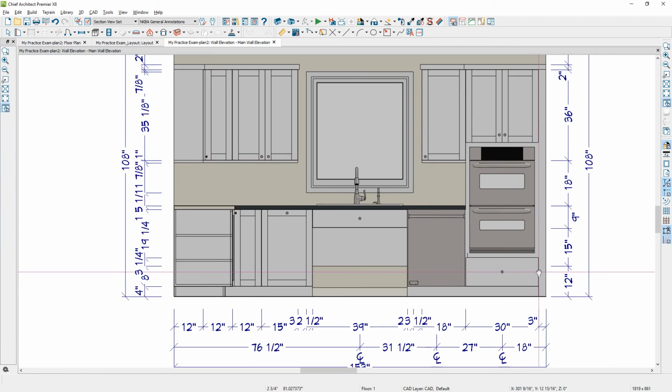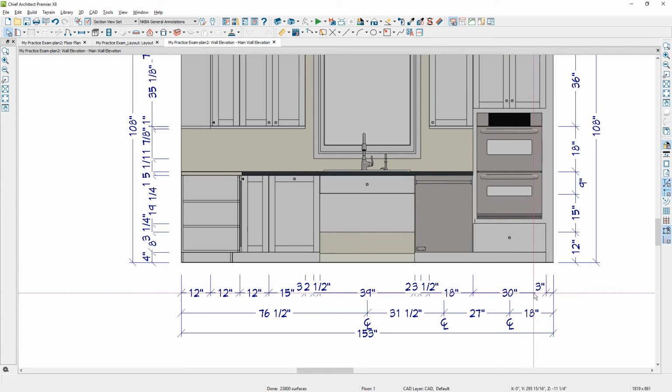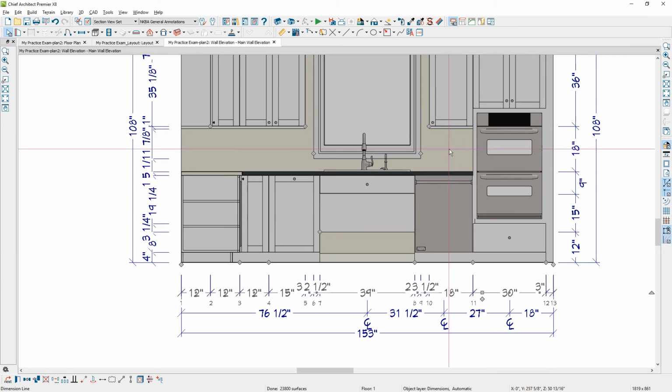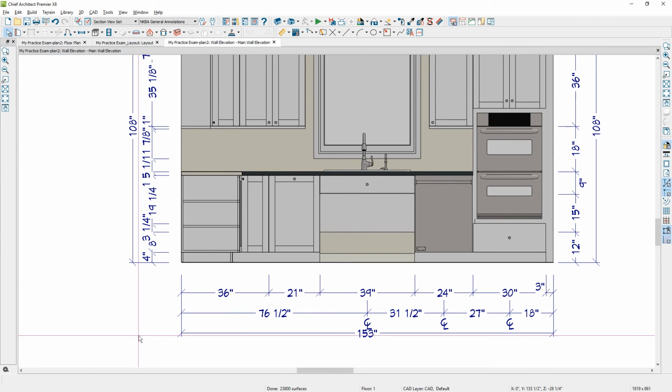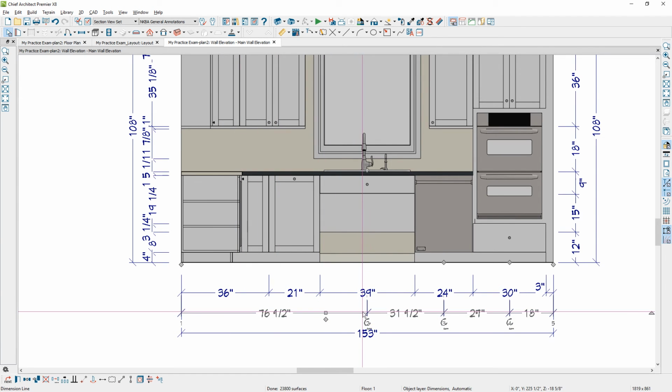Let's move to the bottom. So I've got my 3-inch filler over here. Again, when you select the dimension, you can see that it picked up, for some reason, the wall cabinet, picked up the casing. I'm just pulling those diamonds off, and that will then clean up that string of dimensions. It's picked up the extra corner. Let's go ahead and pull that off, press the space bar, and that looks pretty clean, where it's got mainly just the boxes. We've got the center line for our sink.